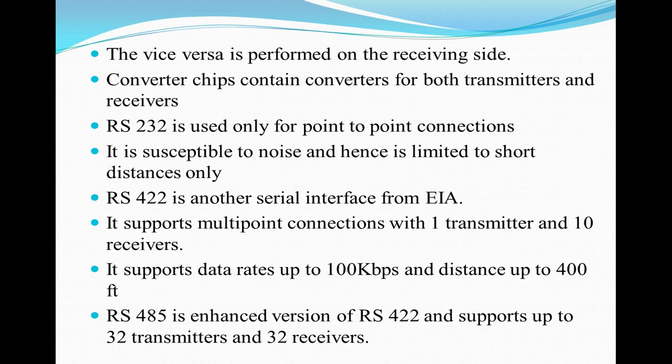With respect to this, the data is transmitted to slave 1 and to slave 2. This slave 1 could be, for example, a serial EEPROM, and this is the I2C device. So the clock is being transmitted as well as the serial data. Likewise, from the master to the slaves, with the help of these two buses, the data can be transmitted or received.